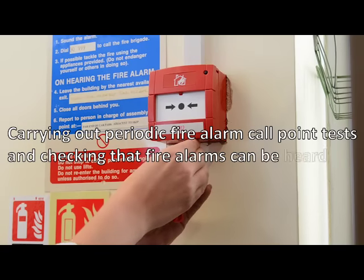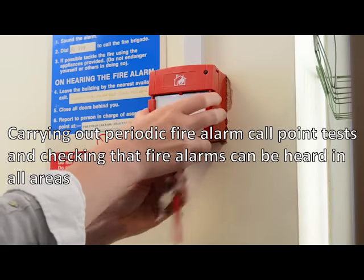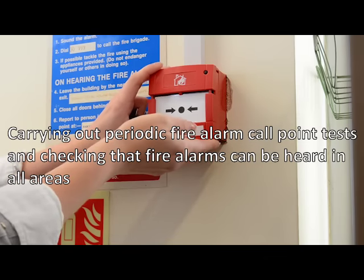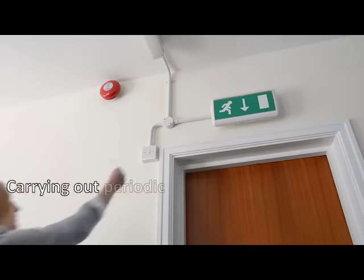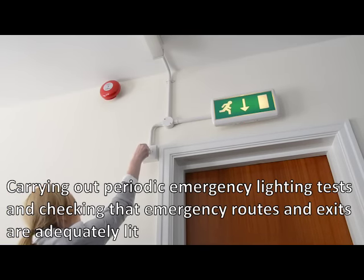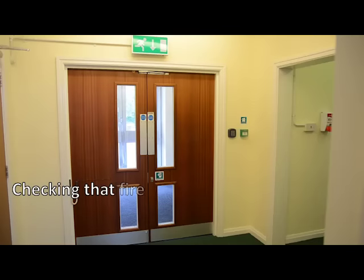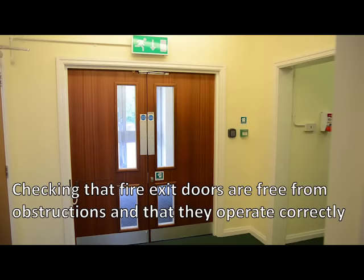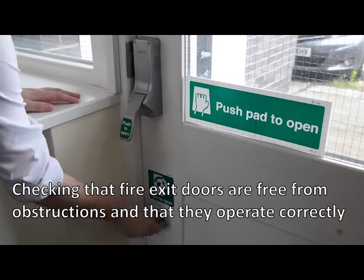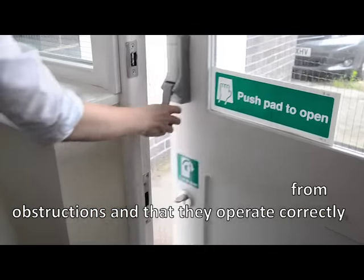Carrying out periodic fire alarm call point tests and checking that the fire alarms and other means of raising the alarm can be heard in all areas. Carrying out periodic emergency lighting tests and checking that emergency routes and exits are adequately lit in the case of failure of normal lighting. Checking that fire exit doors are free from obstructions. This includes inside and outside the building, and that the doors operate correctly.